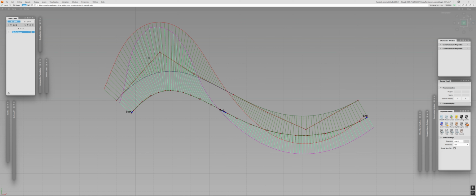As this curve has so many spans, it brings irregularity to the curve. Even though the distances are very close to each other, and in this regard the tool did its job, the surface itself and its curvature are actually quite distorted. So you're going to see this wobbling, right? Here and then here.